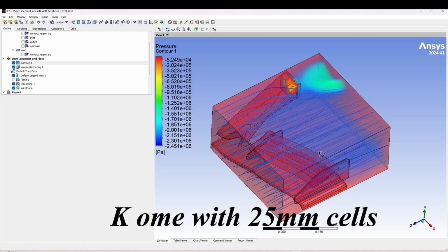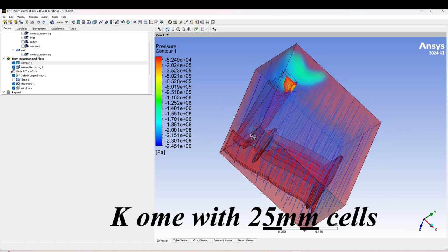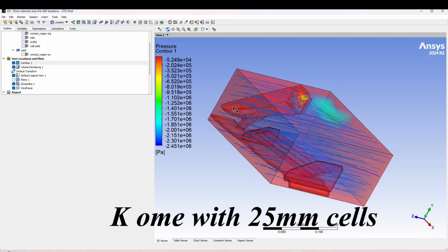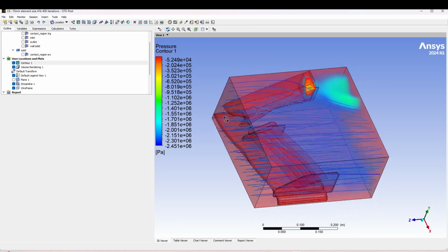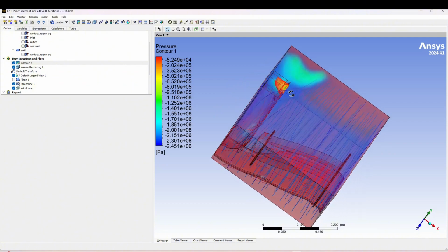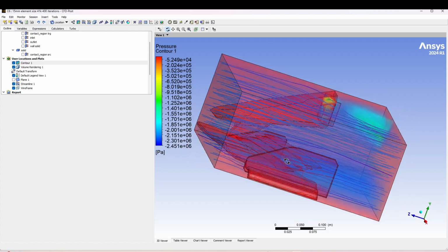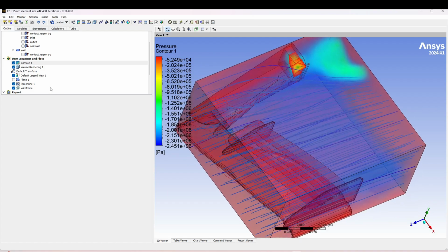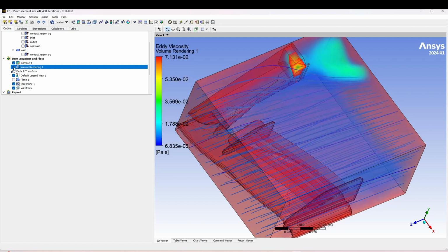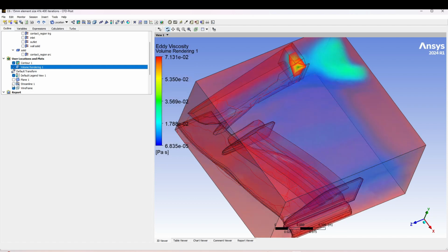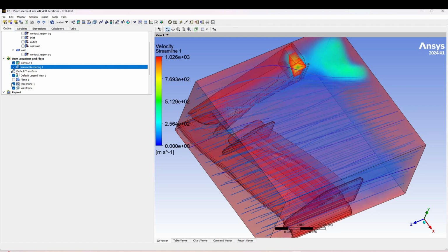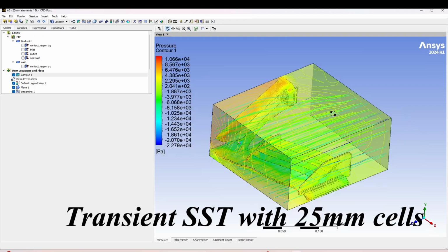Since it is a symmetric part, only half will be used to set up the simulation as the flow is aligned with the body. This will not be applicable in case of angled flow when the car is turning. The flow models used are k-Epsilon, Transient Shear Stress, and Reynolds Stress for the purpose of evaluating multiple schemes. The inlet air velocity is set to 100 meters per second.